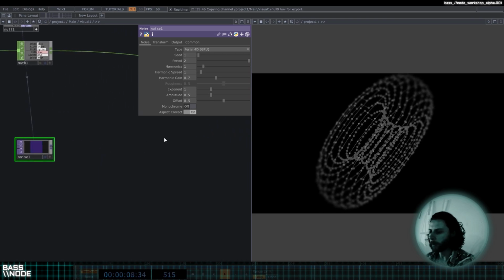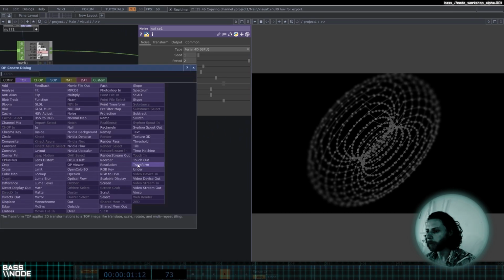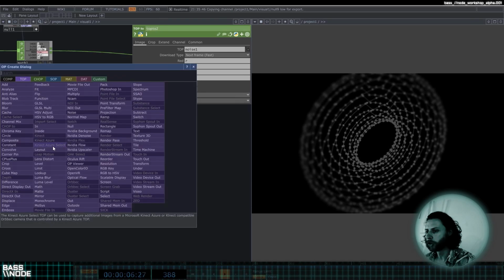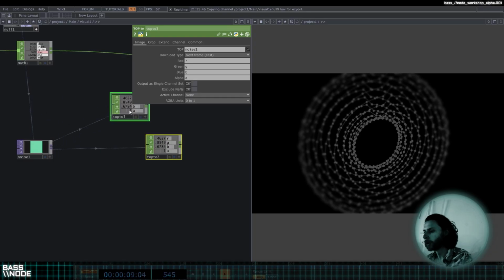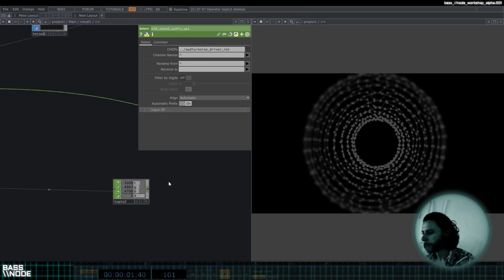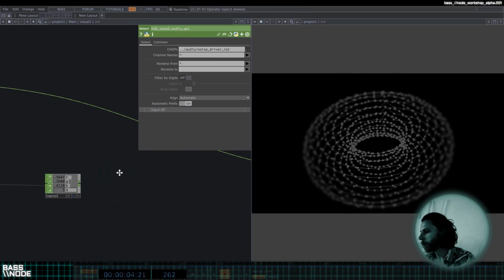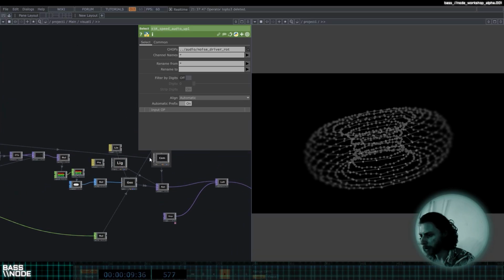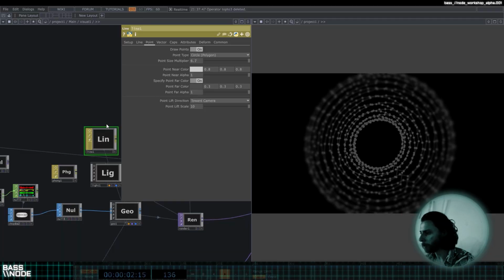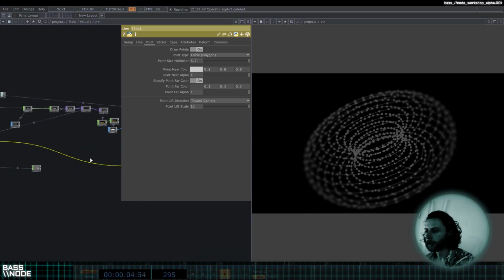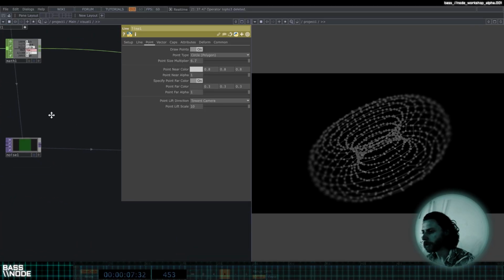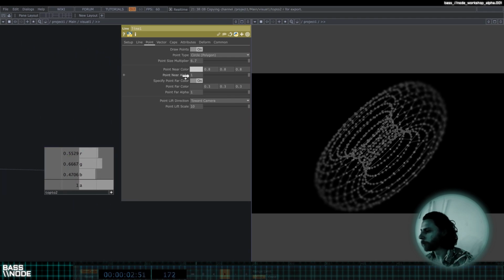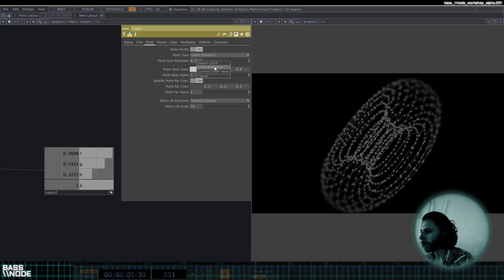And then I'm going to transform this noise into a CHOP so that I can refer to it. So I just right click here, click on the CHOP, TOP to CHOP, and we get our colors in an RGB value. And we'll take those RGB values and find our material, so our line material over here. And we're gonna make our points the color of this noise. And so all we have to do is make the viewer active, click and drag, and then we're gonna put the R in this first one, which is our R parameter.